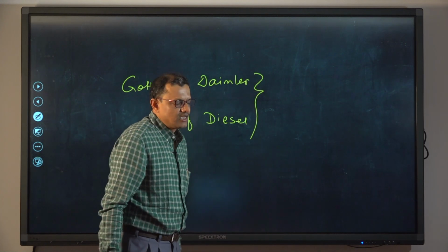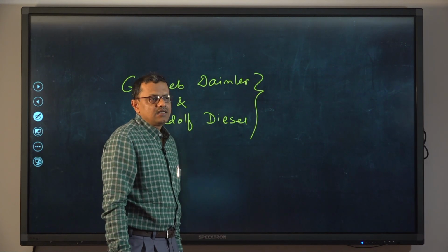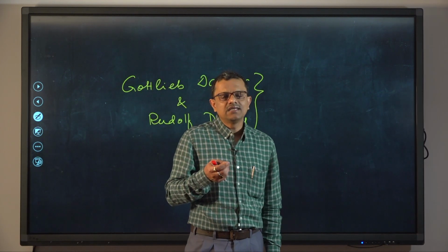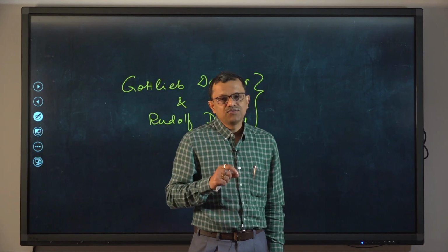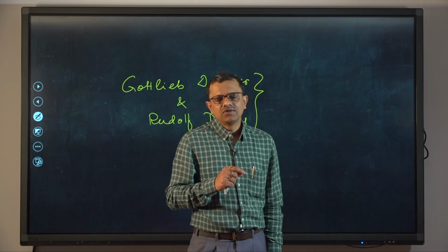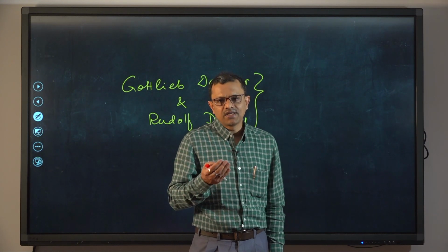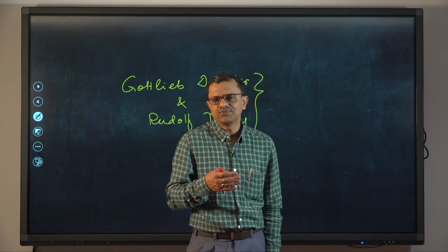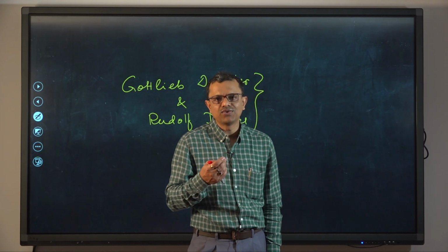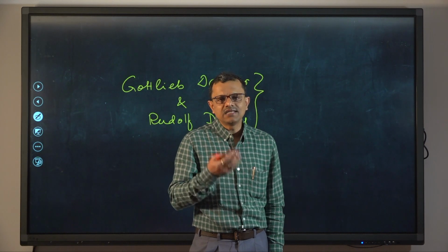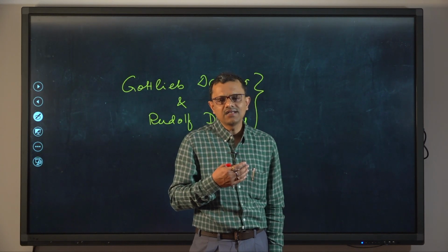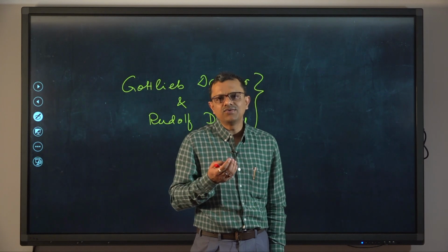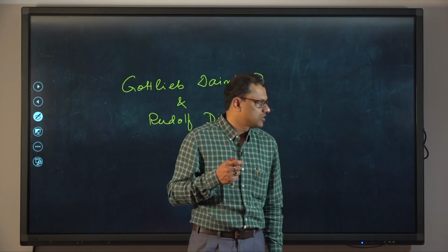Okay? Because if we recall, the amount of air that will be drawn into the engine cylinder is essentially determined by the volume, or displacement volume. So, if you would like to increase the mass of air, we have to increase the density of intake air. For a fixed volume, if we increase the density of intake air, the mass will increase, and if we can increase the mass of air, a larger amount of fuel can be ignited, which in turn will ensure greater power output.